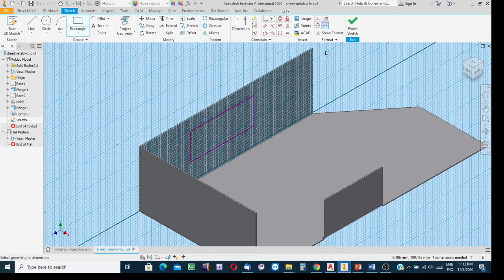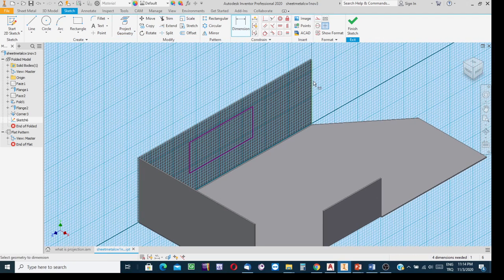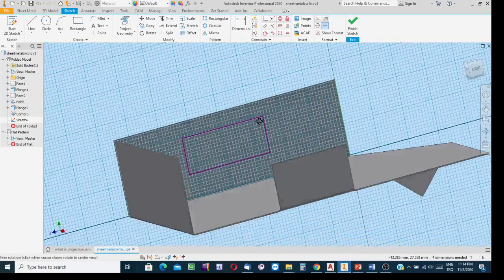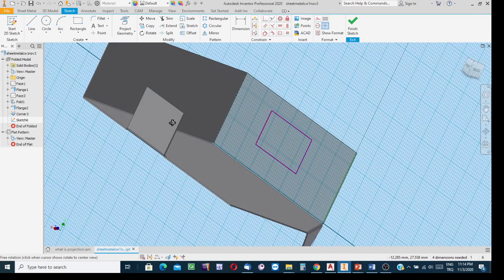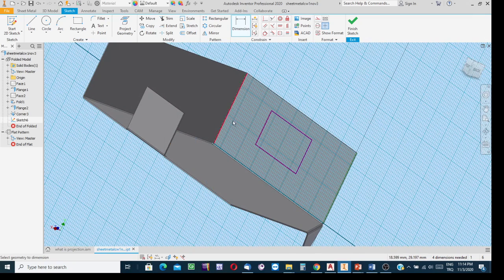Well, I'm going to locate this empty space relative to this edge. So first apply projection process, have the projection of this edge, yes, this projection is sufficient, okay, for inputting the dimensional constraints. If you want, you can much more easily see, change the angle. Okay, the simulated light source is illuminating the surface, so you can much more easily see what I am doing. Relative to here, this boundary of the empty space, which is the necessary sketch for creating an empty space, is, let's say, equal to 40.